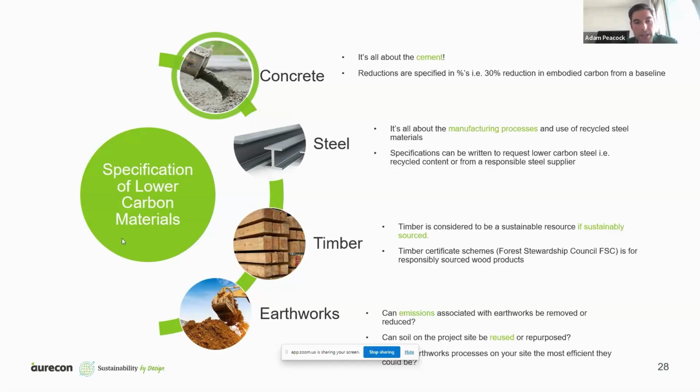And also trying to change the mix design. By reducing the water content, basically it's the water to cement content that gives it the strength. So by reducing the water content, we can reduce the cement content and achieve more sustainability. The only problem with that is that it can be harder to work with. Basically the slump reduces. So super plasticizers can be added to the concrete as well to increase the slump and make it easier to work with.